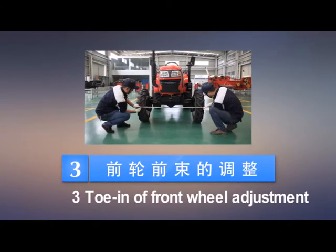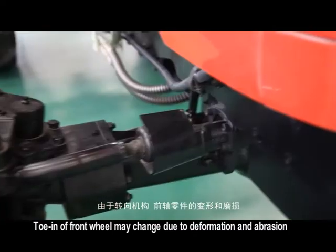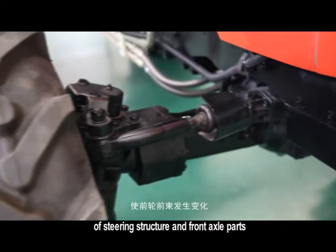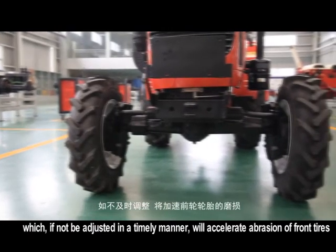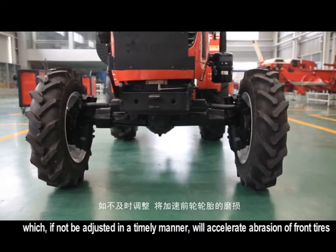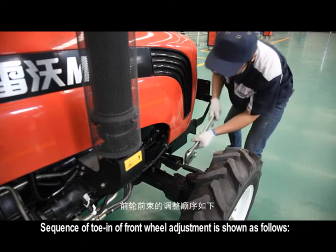3. Toe-in of front wheel adjustment. During operation of the tractor, toe-in of front wheel may change due to deformation and abrasion of steering structure and front axle parts, which, if not adjusted in a timely manner, will accelerate abrasion of front tires. Sequence of toe-in of front wheel adjustment is shown as follows.